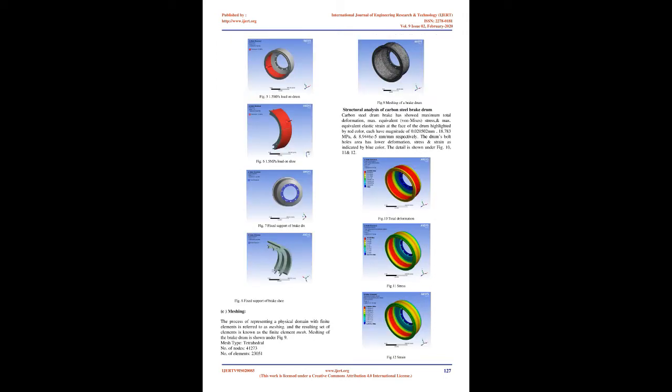In their study to approve the functionality after modification made on the actual brake drum, Anup Kumar and R. Sabarish, 2014, tested the strength and heat removal ability of the brake drum. From the transient temperature test they observed that the temperature is increasing with each cycle. This showed them that the cooling time provided is not sufficient to cool the drum.